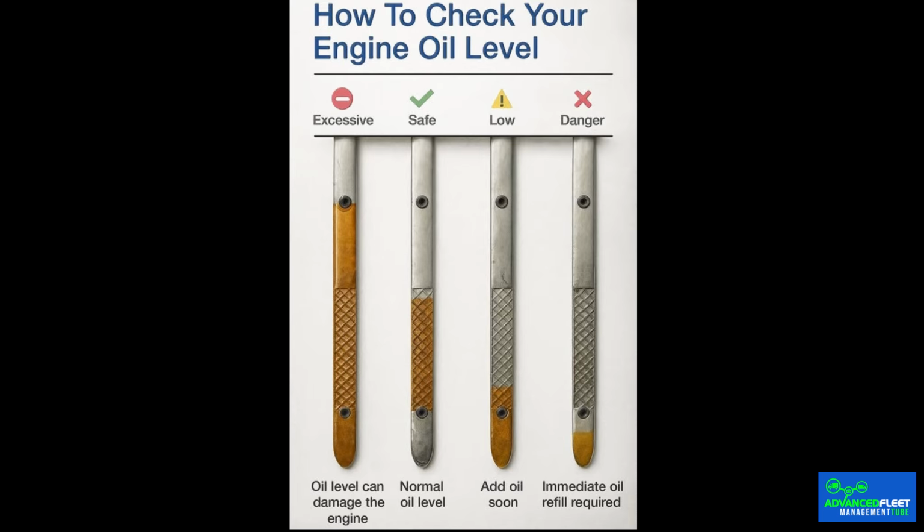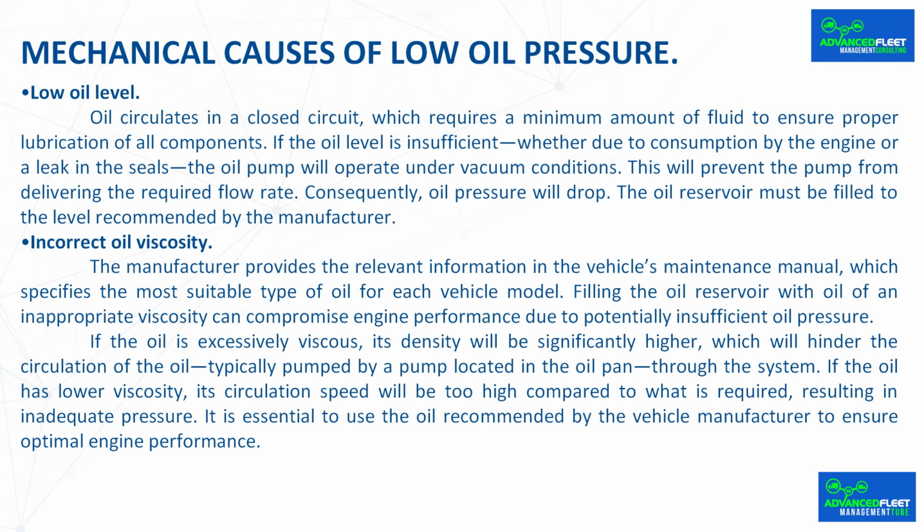The oil reservoir must be filled to the level recommended by the manufacturer. Incorrect oil viscosity. The manufacturer provides the relevant information in the vehicle's maintenance manual, which specifies the most suitable type of oil for each vehicle model. Filling the oil reservoir with oil of an inappropriate viscosity can compromise engine performance due to potentially insufficient oil pressure.